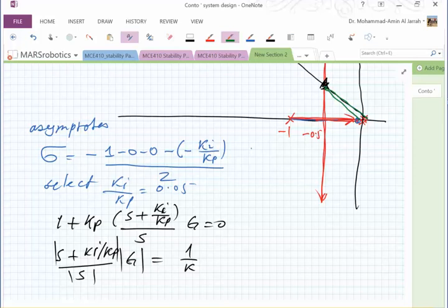Which angle is bigger, the pole angle or the zero angle? I'm talking about the controller. The pole angle is greater. The pole angle is an external angle to the triangle, right? So this angle equals the zero angle plus this angle. So the PID controller needs to maintain a small difference angle. Otherwise, it can make the transient performance very bad.